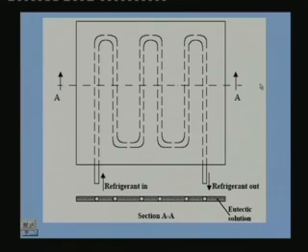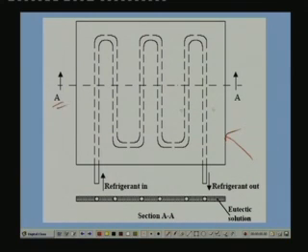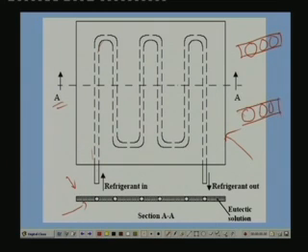Okay, so let me describe this. So you can see here, and this is the cross sectional view at A, right. So if this is like a closed box in which the serpentine refrigerant tube is sandwiched, right. That means you take two plates and put this serpentine coil and close all the edges, and have the inlet and outlet. These are the refrigerant tubes, and this is the plate over which your air flows, or whatever is the external fluid that flows, right.